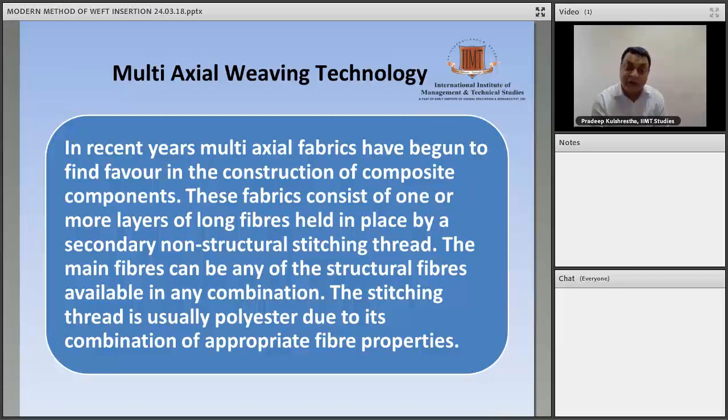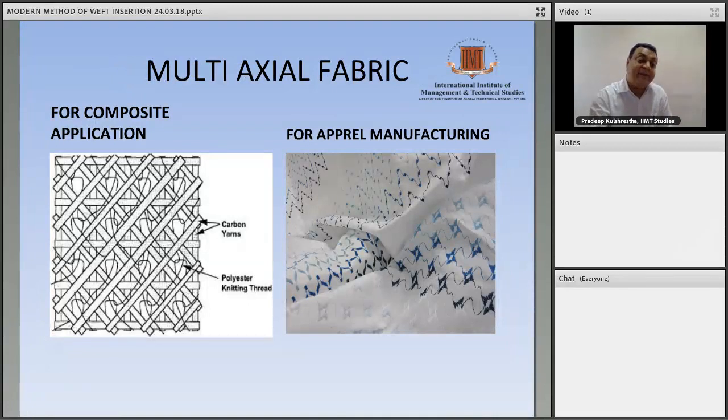So we'll make the multi-axial aramid on the loom. Then we do a further process of lamination to increase some GSM by putting chemicals, then bulletproofing can be done. Bulletproofing cannot be on linear fabrics, but it can be on biaxial fabrics or technical fabrics.